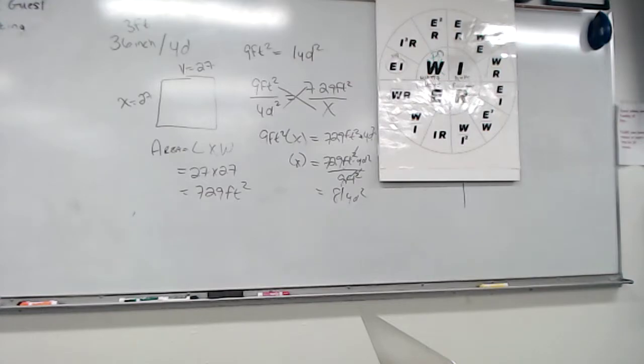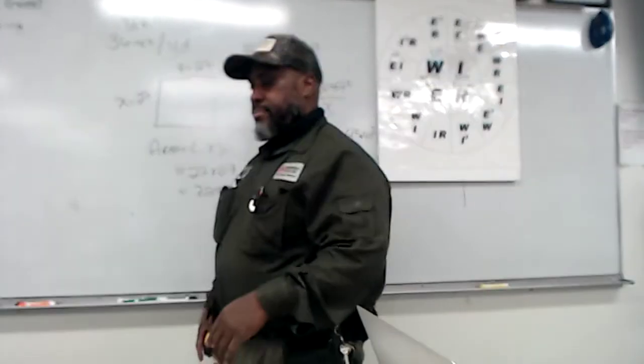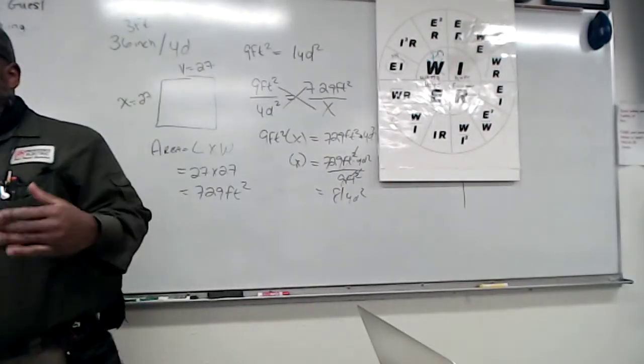Why do they call it a masonry box? Because they rough it in the brick, in the wall. That's how your outside plug at your brick house gets in the wall. You put a masonry box and rough it in. Most times a conduit or MC cable, sometimes flex. All right? Well, it ain't a masonry box because it ain't squared up enough.